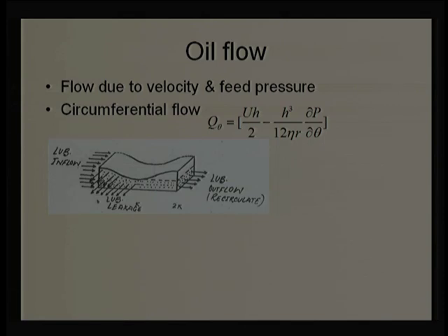That is why we require a flow rate also. The heat generation is there, and it is getting convected and conducted. The simpler one is to assume the conduction is 0, which gives us a slightly conservative design, but that is fine for us. To proceed in that direction, we require the flow rate. We discussed earlier, if there is a hole arrangement or slot arrangement, we can estimate the flow rate, that is QP.